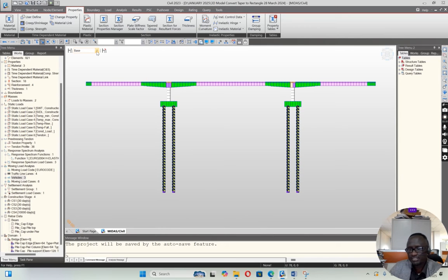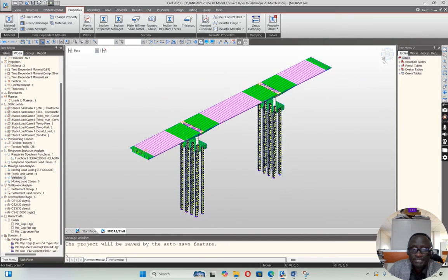You have already fabricated your site. You have where you are cutting your reinforcement, the reinforcement cage, the fabrication yard. Then when you do your drilling and the rest of it, normally we do the piling first, then the pile caps. Then from the pile cap you start working on the pier support. So here is where you need to be careful.